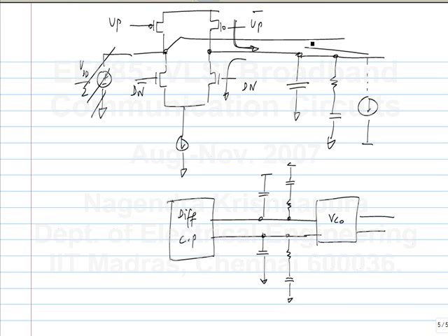Now, I want to detect the phase difference between a clock and certain data, because I can use the same principle, right? How did I get to this circuit? I wanted to align the frequency of the output with the frequency of the input, or some multiple of it. Now my input is not a periodic signal but data. I want to generate a periodic output whose frequency is exactly the same as that of the data. So I can use the same principle, that I can detect the phase difference between clock and data, but how do I do that? The counter after a certain accumulation increases this. How will that help? Is the question clear?